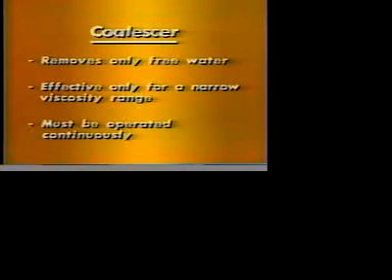These coalescers, utilizing cartridges, are affected by the properties of the hydrocarbons, specifically the interfacial tension, which tries to keep the hydrocarbon particle and the air particle, if you want to call it that, together. They are efficient and effective for a relatively narrow range of lube oil viscosities. However, it's true that they are very cost effective. We, for our part, must realize they remove only free water.